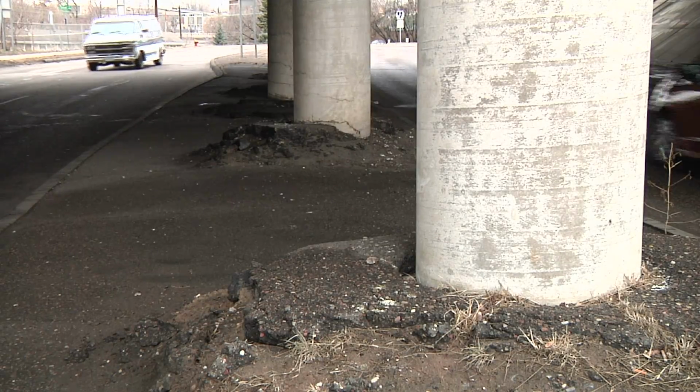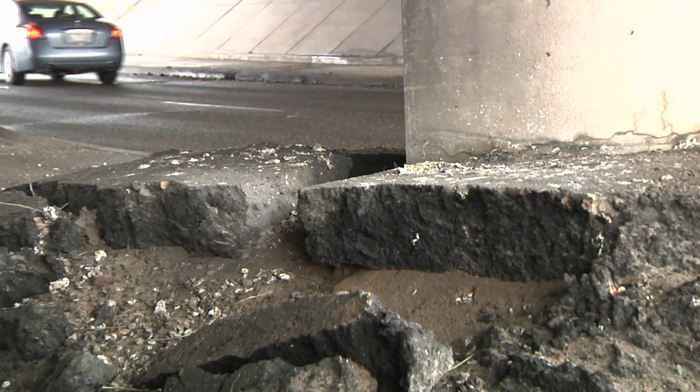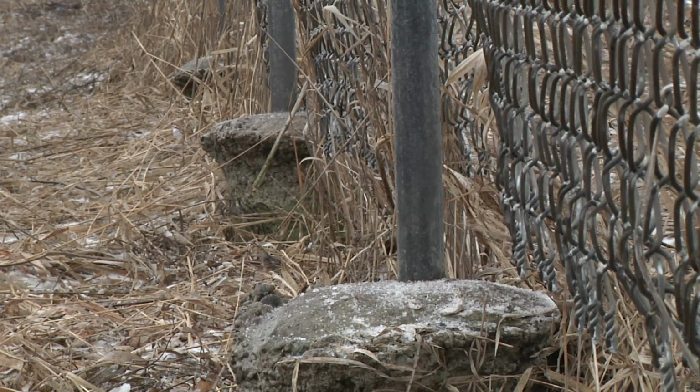Frost action can also lift almost anything embedded in soil that's above the frost line, such as foundation pilings, utility poles, and fence posts. We can see how that happens in this experiment where dowels represent pilings. A barely visible void appears beneath the larger dowel as it begins to lift.